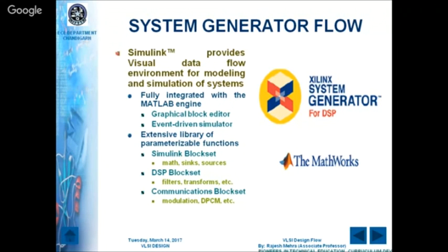So in this way you have to convert, and this conversion is basically performed with the help of this software, System Generator and AccelDSP. They convert this floating point data into fixed point data in the form of 0 and 1, and then they generate VHDL or Verilog code for you, right? So with the help of System Generator, we can generate VHDL code or Verilog code for our model.